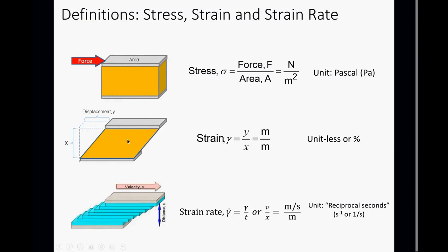Okay, if we don't have a solid in here, imagine we have a liquid instead, and we apply a stress to a liquid, then what we're going to see is an onset of deformation, but that strain is just going to keep on increasing with time. So then we can define and quantify a strain rate or a shear rate here. And so shear rate or strain rate, they're one and the same. This is basically the rate of change of strain with time. Another way to think about shear rate is it's the velocity gradient. So it's the velocity divided by the thickness of that shear field there. And this can be useful when it comes to making decisions as to appropriate shear conditions in which to run a specific test.